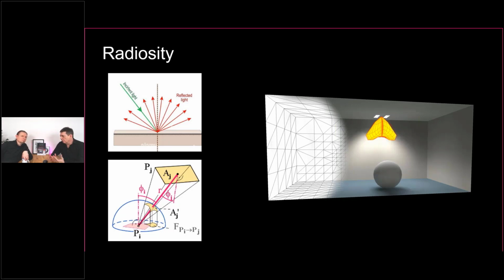So we assume this in this situation. We have a perfectly diffuse reflection, and only in this situation it works. In most planning situations, this is good enough. Just if you have a room filled with mirrors, then you will have a problem. But for standard rooms, standard offices, standard floors, we typically have a more or less diffuse situation. So radiosity is the main calculation core.